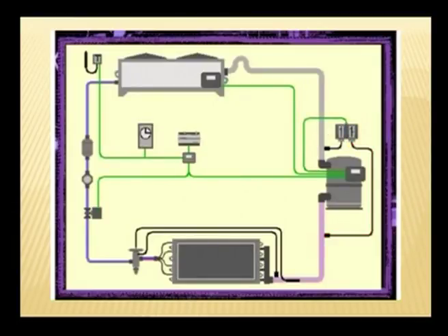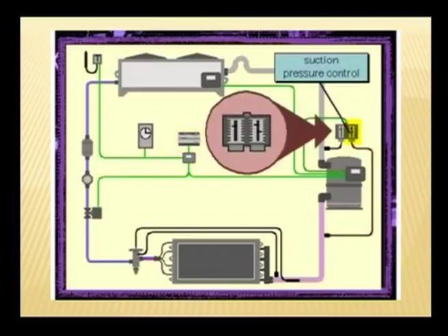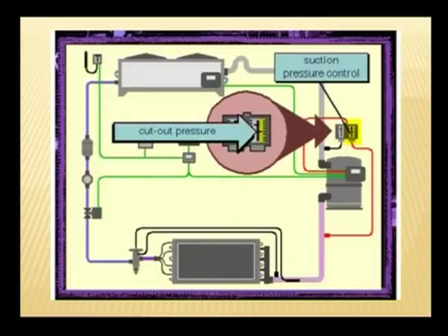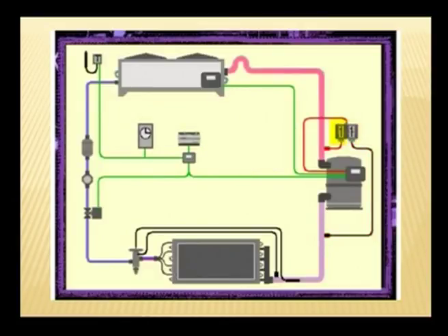The compressor can be shut off by one of the three following controls. The first is a room thermostat. This thermostat shuts off the compressor if the ambient temperature is lower than the set point temperature. The second is the pressure control that measures the minimum required pressure at the suction inlet. This means if too little refrigerant is coming from the evaporator, the compressor will be stopped. This is the cutoff pressure.